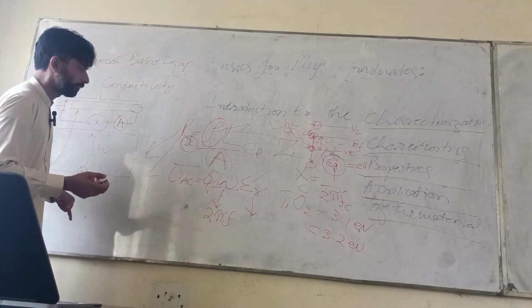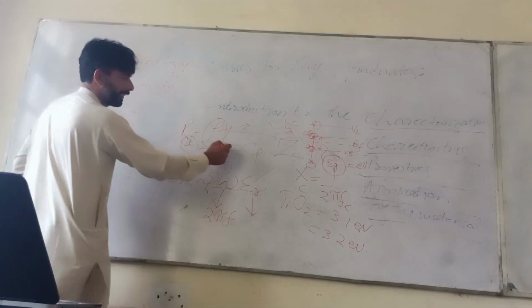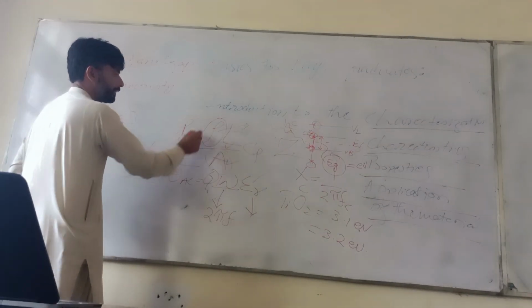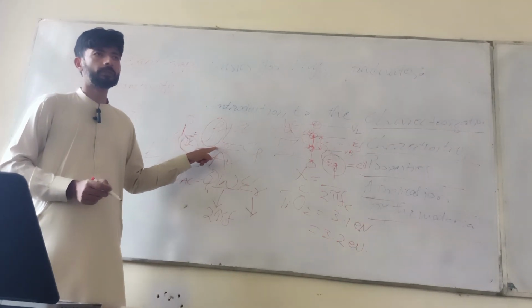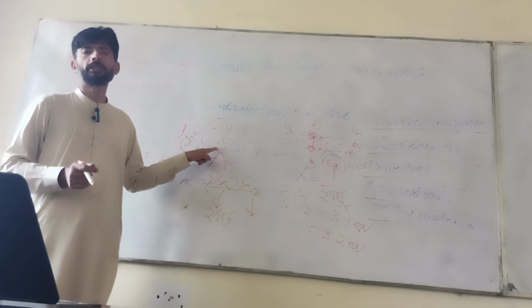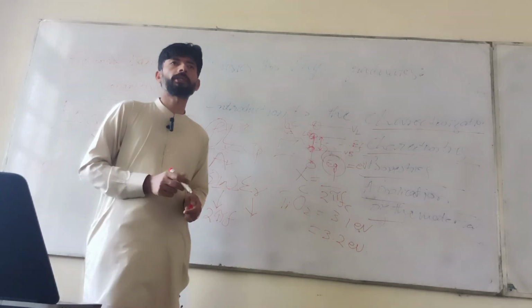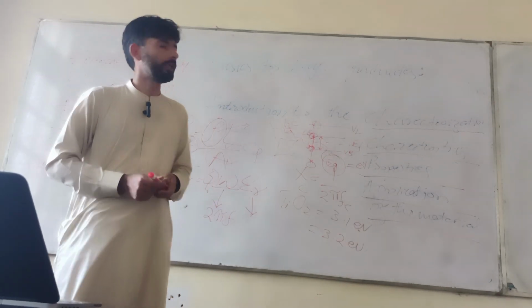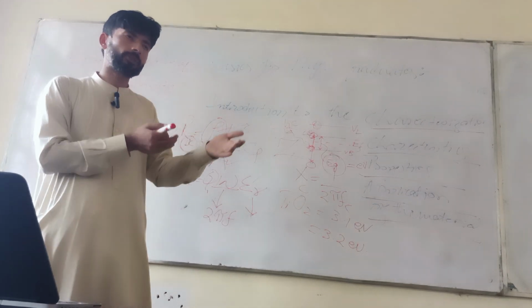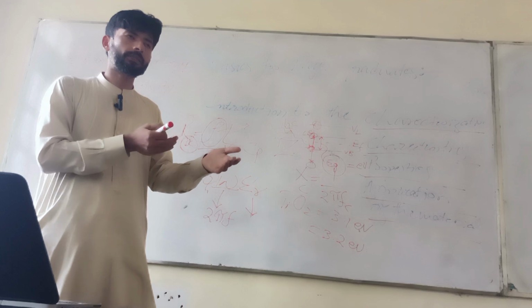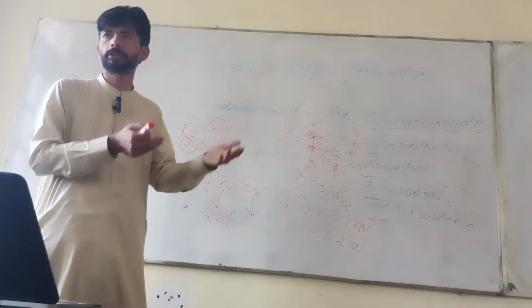Alternatively, if you know the L, and if you know the A, and this is derived, what is your end product? Resistivity. That is the property of your material. If you don't know your material, just derive this and state that this is planar material, this is copper, this is aluminum, this is tungsten, this is gold.